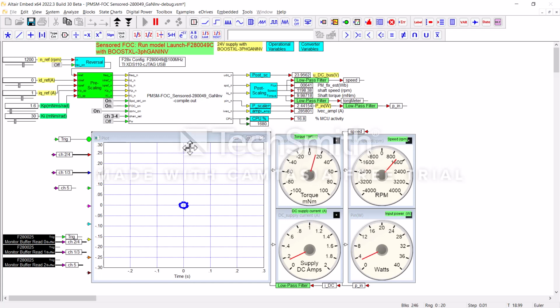Now, I can pick the motor up. You can hear the little bit of tape flying around. I can slow the motor down. I can speed it up. We can turn on field weakening, and you can hear the motor speed up a little bit. It's off. So without field weakening, we're at about 2,000 RPM. Bump it up, we're starting to get to 24. So we get a couple hundred RPM out of it. But if you look, you can see the watts jump up to almost 16 watts, turn it off for almost 8 watts. So double the power for not much speed increase, so you really got to need that speed increase. Maybe you're in your Tesla and you want to win a drag race or something.